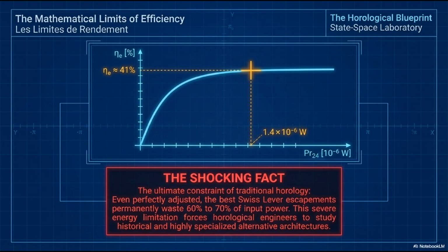5 improvement approaches are being pursued. First, reduce contact time, shorter lift angles mean less sliding friction per beat. Second, minimize friction, silicon pallet stones and escape wheels have lower friction coefficients than ruby-on-steel, require no lubrication, and maintain dimensions over millions of cycles without degradation.